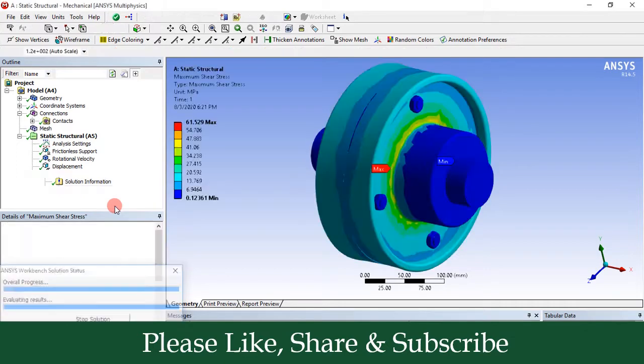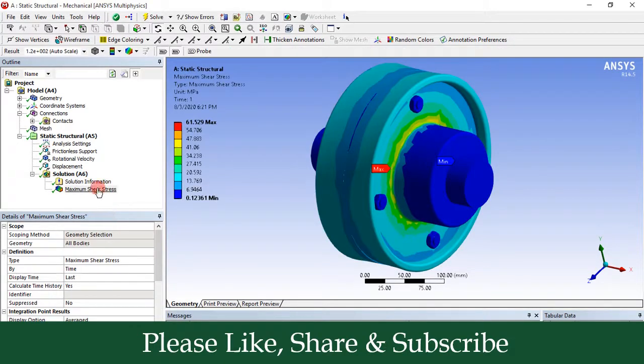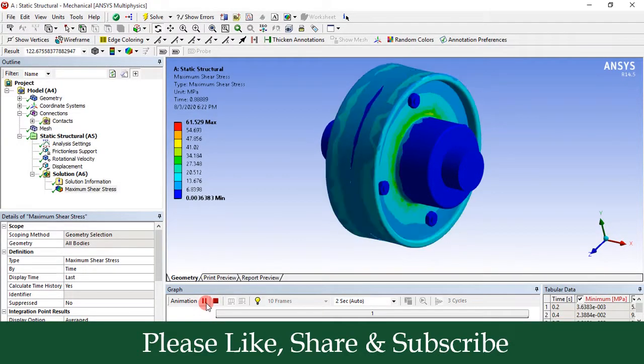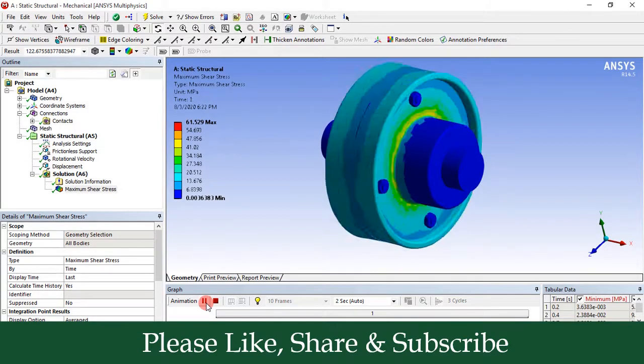So it will take some time to solve this output parameter. So you can see here maximum shear stress value is 61.529 megapascal. So this is the overall result for this maximum shear stress for this coupling. So let us play this animation. So you can see how this shear stress is varying in this coupling.